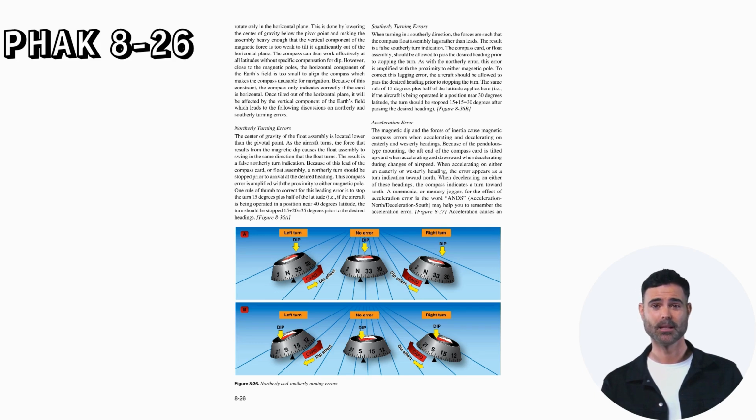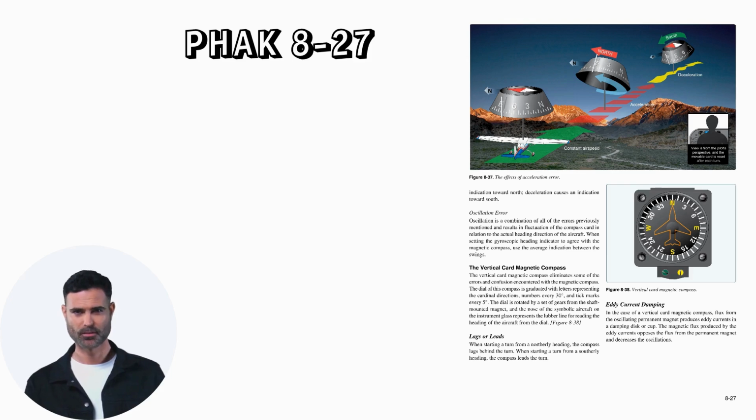A mnemonic or memory jogger for the effect of acceleration error is the word ANDS: acceleration, north; deceleration, south. This may help you to remember the acceleration error. Acceleration causes an indication toward north. Deceleration causes an indication toward south.